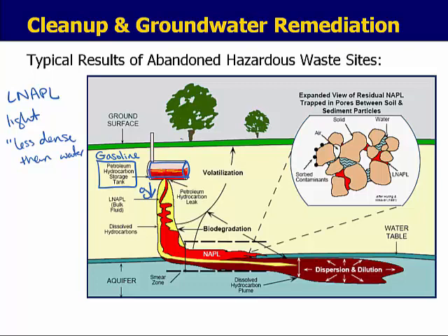The rate at which this moves is totally dependent on the hydraulic conductivity K of the subsurface, which is a function of the geologic properties, and also the presence of water, or bulk fluid that moves the hydrocarbon. In this scenario, you'll see a concentrated plume, denoted by the red, and around that plume, you'll have a lesser concentration that's being caused by dispersion and dilution.